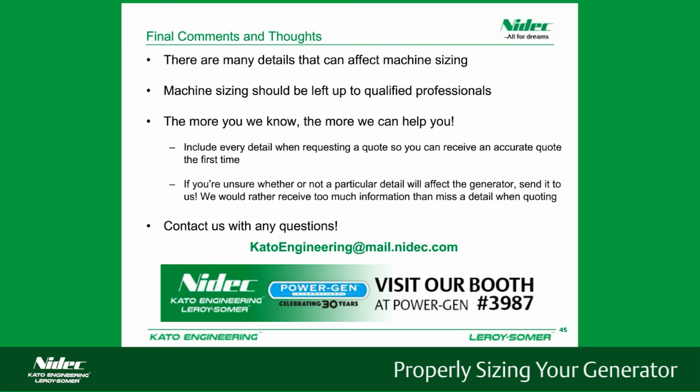As far as being able to handle more of a capacitive load, we'll need to oversaturate the machine. Oversaturating can drive a larger size machine, but also a larger machine will be able to handle more capacitive load without having to be derated.